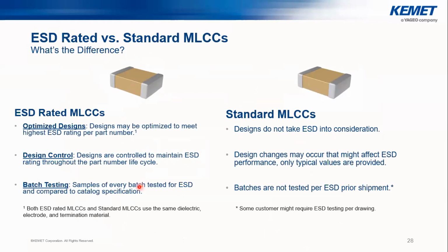The designs are controlled to maintain the ESD rating through the whole life cycle of the part numbers, whereas standard ones might change and don't mention the ESD performance. Also, for these ESD-specific series, every batch is tested for ESD.